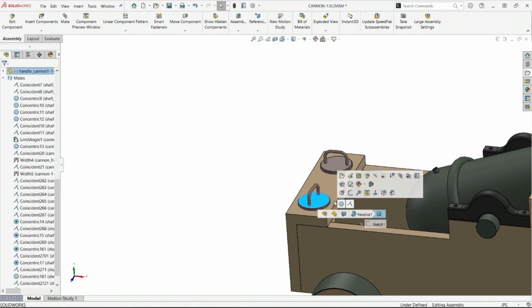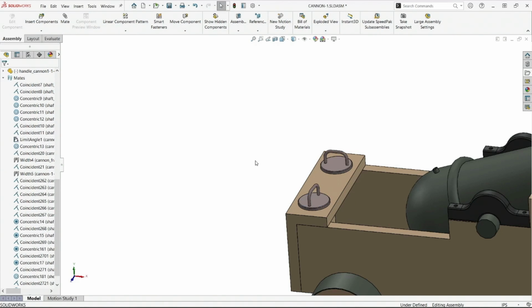Are there any toolbox users out there? Use SOLIDWORKS Toolbox? You drag those in and they snap into place. If you look at your toolbox parts, they have that mate references folder there. But you can build those into other components as well.